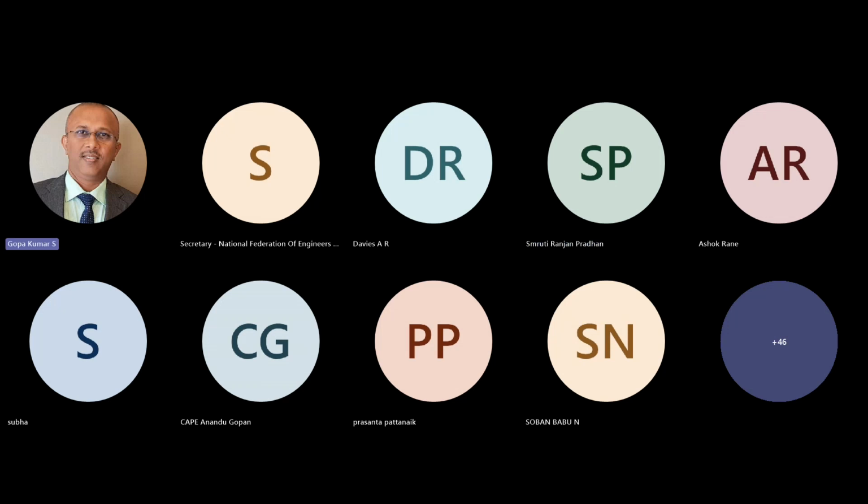I cannot answer it because I don't know the reliability of the armoring and the bonding and all. IS 3043 is not allowing armoring to be used as a fault return path. So, sir, we have to install a separate permanent earth conductor. Earth is the best conductor.